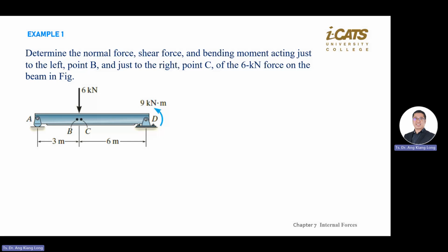A is like a roller, like a ball. You imagine there's always only one contact point here, and it is always 90 degrees. So for the external force, you draw here A equal to Ay. Then look at D. D is not a roller, but there's a pin there.